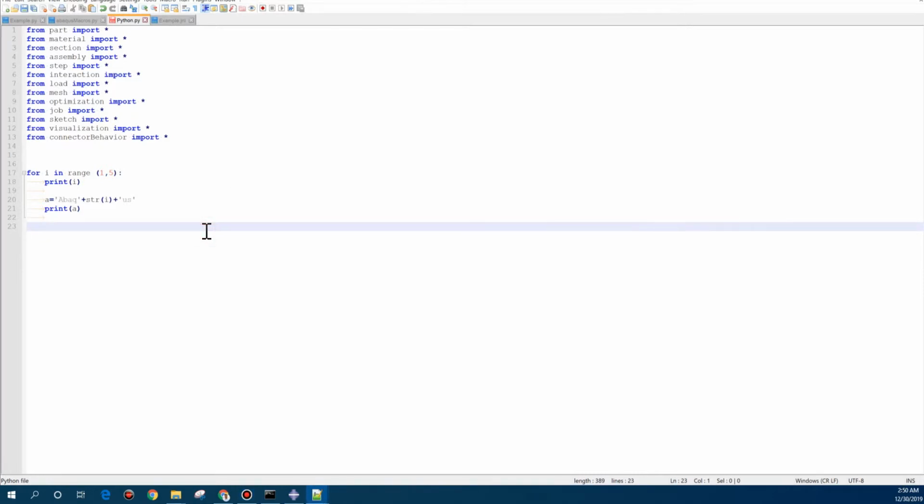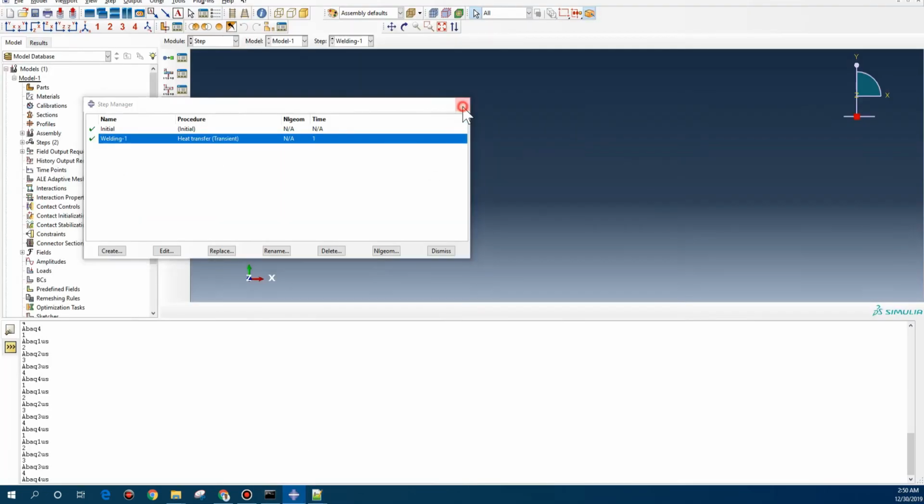If you need more examples, I have another example for modeling additive manufacturing and welding processes. In both models, we need to add material, and for adding material, we need to use Python code for the element birth technique, which is very common.